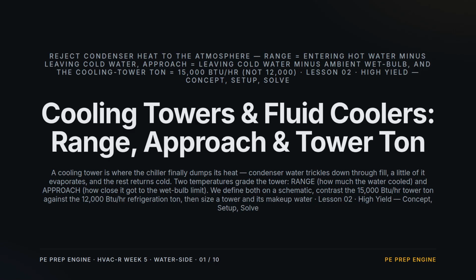Week 5, Lesson 2, Cooling Towers and Fluid Coolers. This is where the chiller finally rejects its heat. Condenser water trickles down through the fill, a little of it evaporates, and the rest comes back cold. Two temperatures grade the tower: range, how much the water cooled, and approach, how close it got to the wet bulb limit. We'll define both on a schematic.